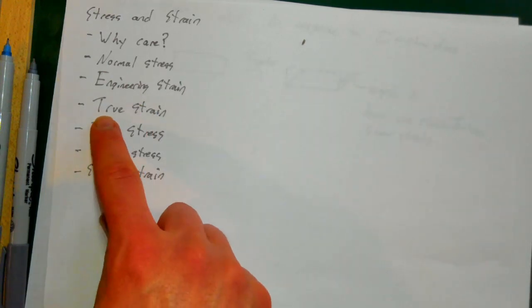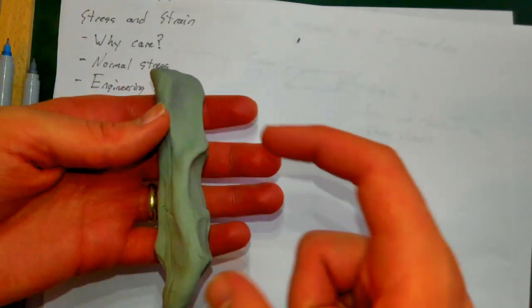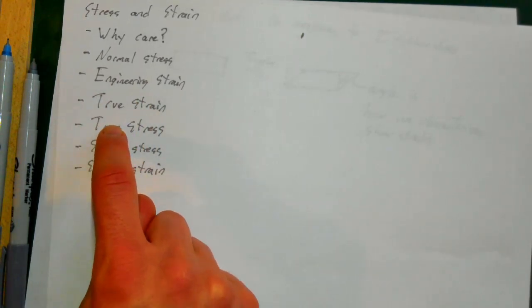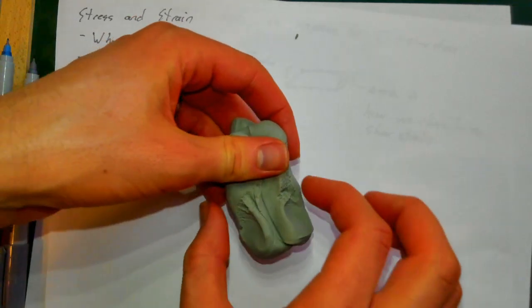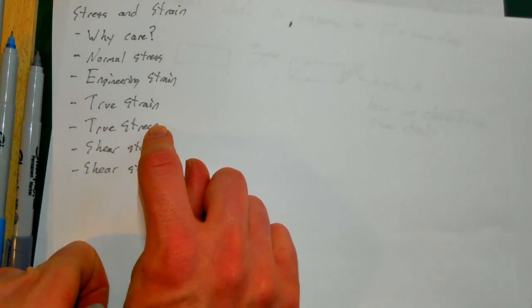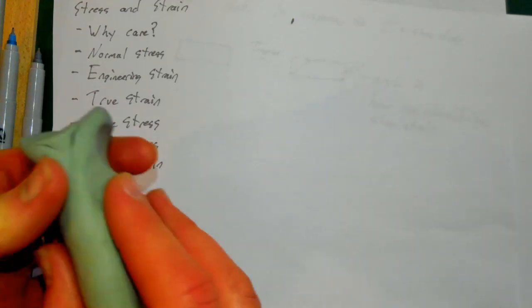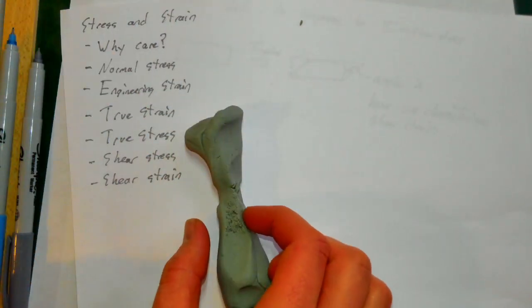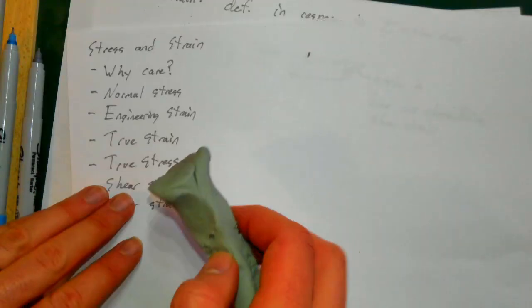There's a natural log in there, but that basically says, hey, that last little bit of strain that you did doesn't really count as much as that first little bit of strain that you did. So let's characterize things that way. True stress says, hey, wait a second, you don't want to divide by the original area, you want to divide by its current area if you want to predict what's truly going on. So the true stress has a correction factor that allows you to predict how much stress a material might have when its cross-sectional area has decreased due to stretching or increased due to compression.